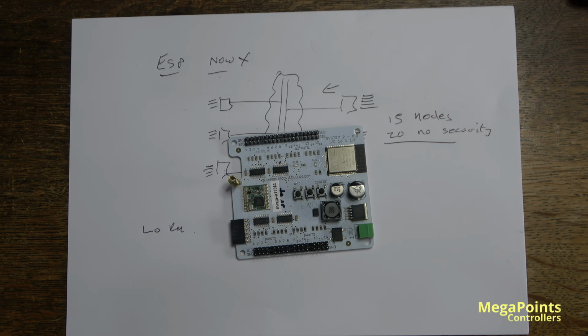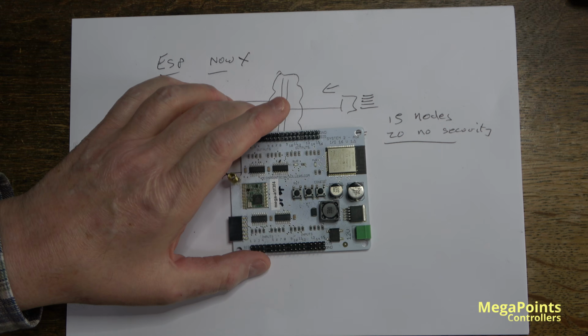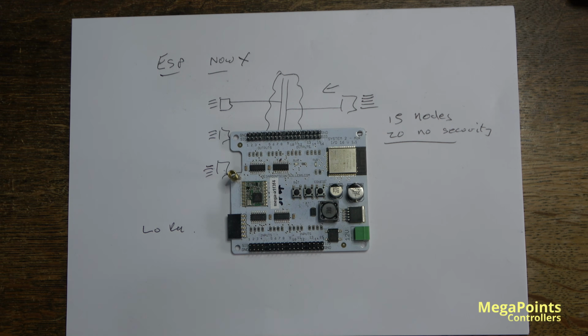And that means basically you can only send data at a specific rate, and it might be, for example, send a packet out and then we can't transmit anything for another 20 or 30 seconds on this device because it doesn't meet the specification. Or we use a different part of the band and we use a much reduced power setting, and then there is no duty cycle requirement and we can send data all day long at any rate at all.